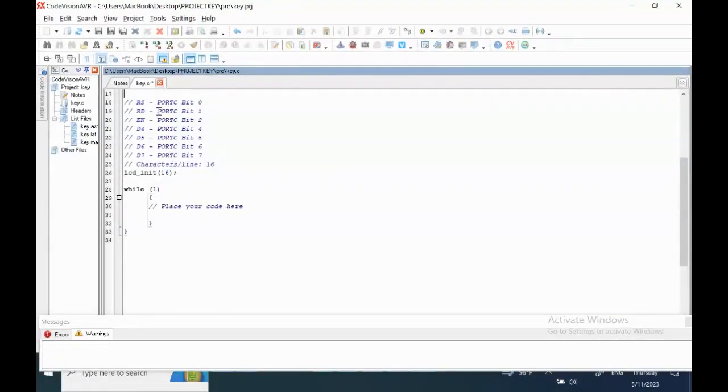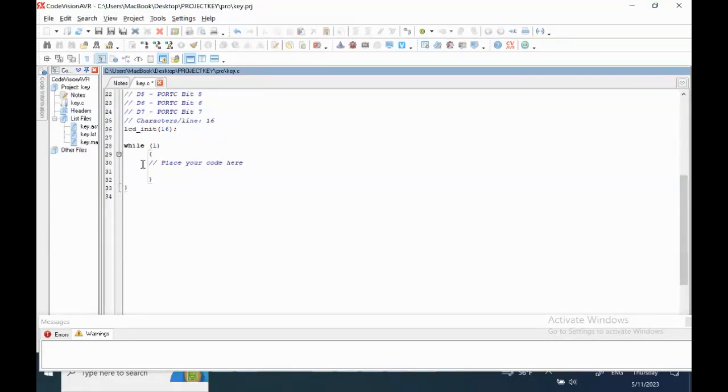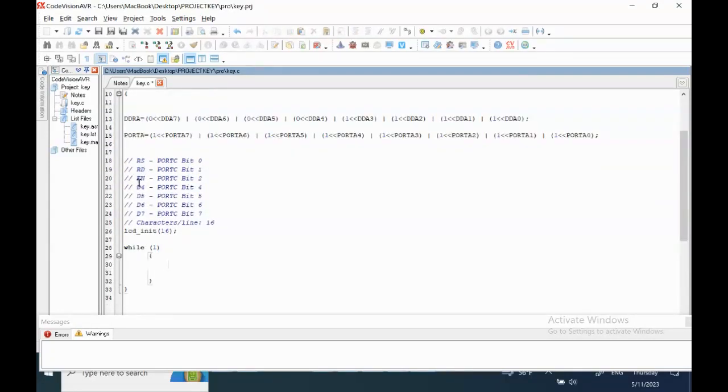Port C is enabled. We enabled LCD in port C, and we initialized it. You see that the code related to initializing of LCD is generated by CodeWizard. Also, we can erase this part. And we said that it is better to not erase the connections because we are using them in our simulation and also experimental results.